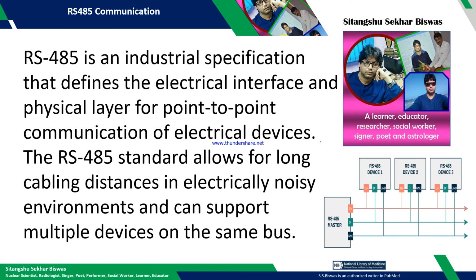So RS-485 communication is an industrial specification that defines the electrical interface and physical layer for point-to-point communication of electrical devices. The RS-485 standard allows for long cabling distance in electrically noisy environments and can support multiple devices on the same bus.